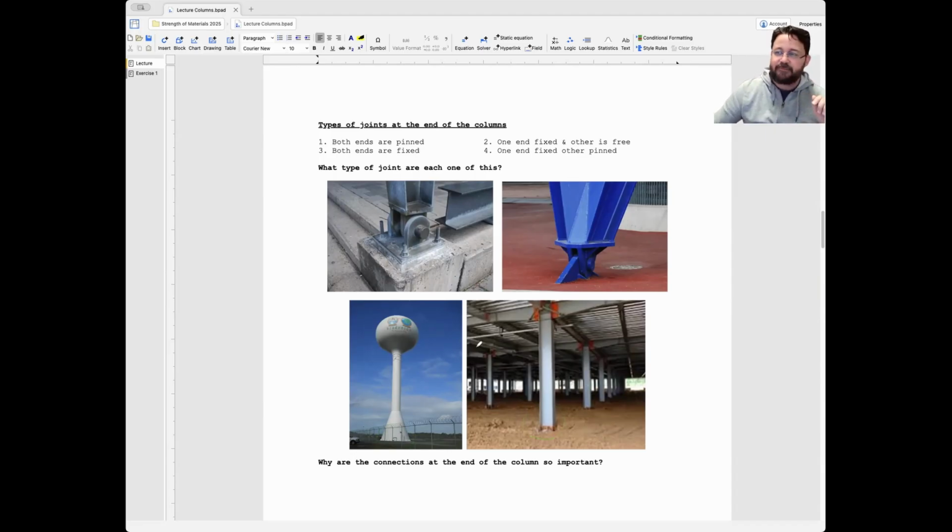That's a nice question. I think it has more to do with the design, and I'm going to show you a table in the next pages that is going to clarify many things about this. But for example, if you are designing a water tank, you wouldn't put a pin joint here because there's no stability. So if you want to be very engineering about it, the type of joint depends on guaranteeing the stability of the structure, the equilibrium of the structure.